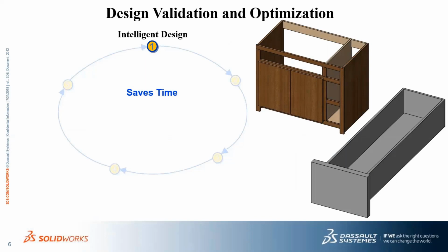Weldments allow us to create and store a variety of standard and custom profiles, while simultaneously affording us the controlled precision that we can use to quickly complete our cabinet designs. Equations give us the power to create template parts that we can then quickly change to our desired specifications, eliminating the need to model each design variation.